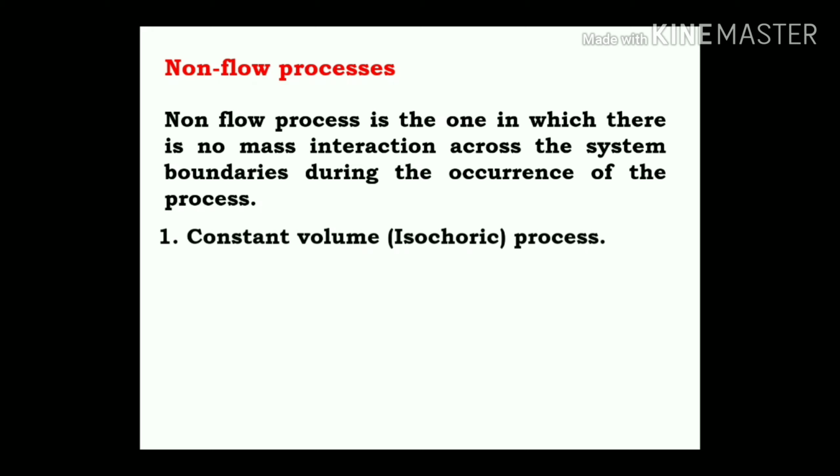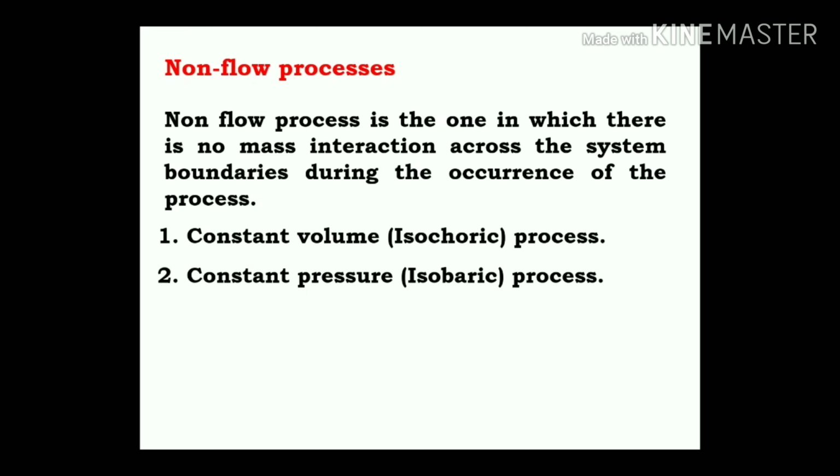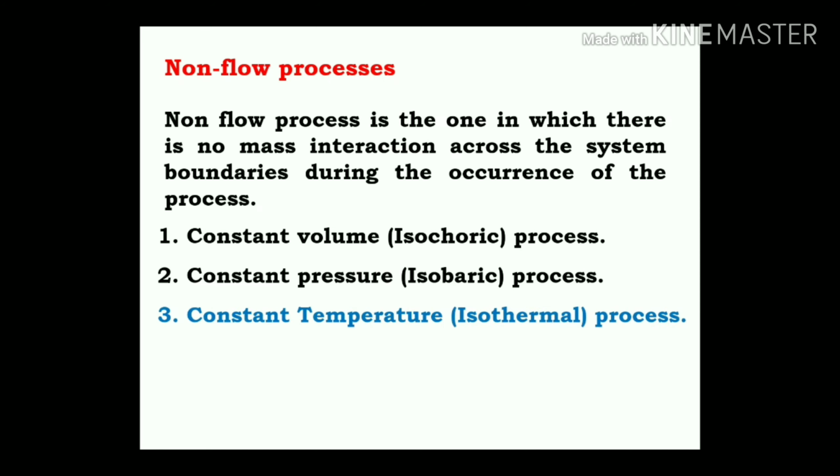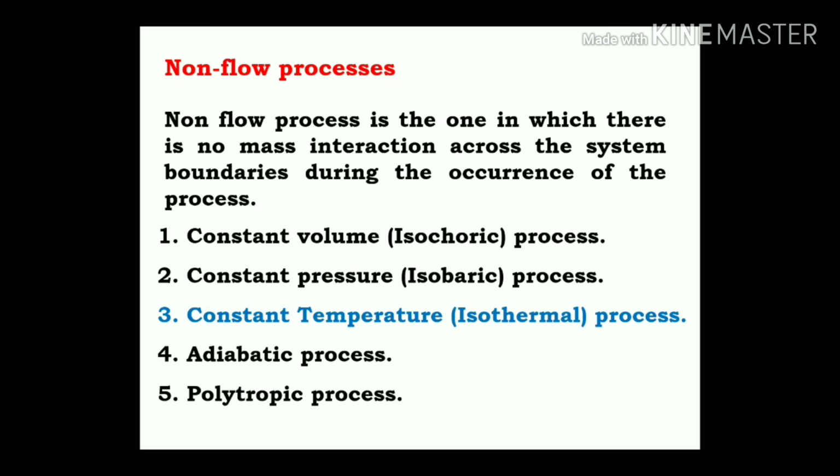So there are a number of non-flow processes. The first one is the constant volume process, or you can say the isochoric process. The second one is the constant pressure process, or isobaric process. Then the constant temperature process, or isothermal process. Today we will only be focusing on the constant temperature process, or isothermal process. Then one more, the adiabatic process, in which there is no heat transfer. And fifth, the polytropic processes.